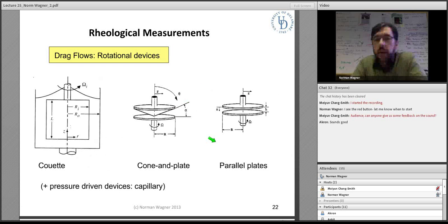And finally, I just want to mention the way in which rheology is done, which is relevant for doing Rheo-SANS measurements. We can typically use a rotational device, although we can also push fluids through a pipe, as I showed you also with the cross-slot flow device that we talked about earlier. The most common devices are, for example, a Couette device where one rotates the inner cylinder and the fluid is confined in between. And I'll show you some of those later.